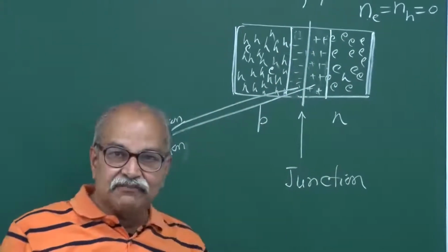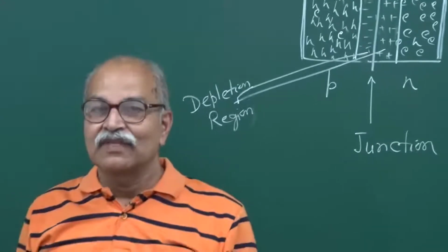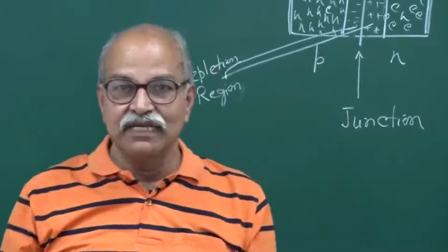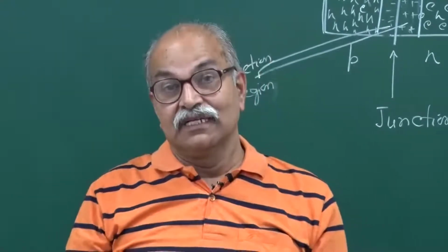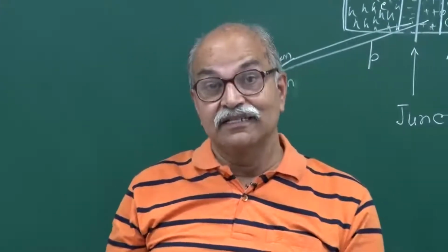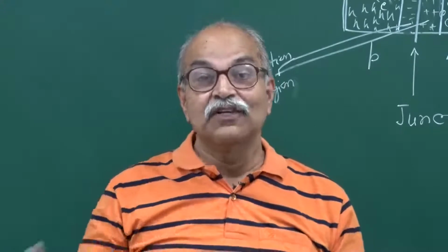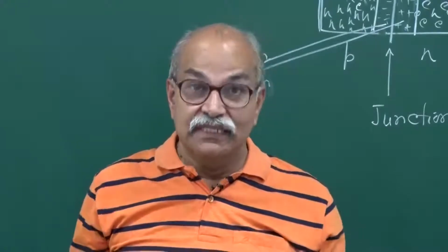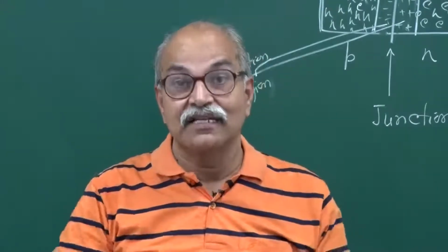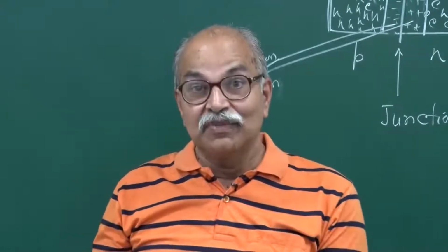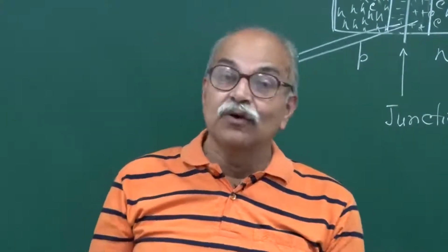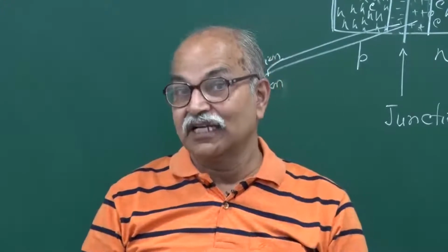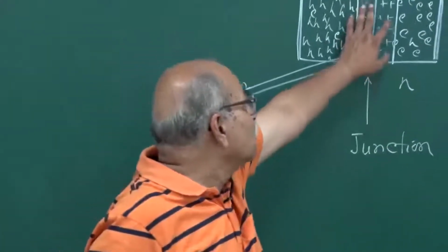But then at any temperature, we told earlier, new hole electron pairs are created, because in that material you have a thermal distribution. These electrons can get energy from the crystal of the order of the Boltzmann constant k times T. So because of that thermal distribution, energies are taken up, energies are given away. So new electron hole pairs are always created, and old hole electron pairs are destroyed in a normal semiconductor. So that process is still here in this depletion region also.